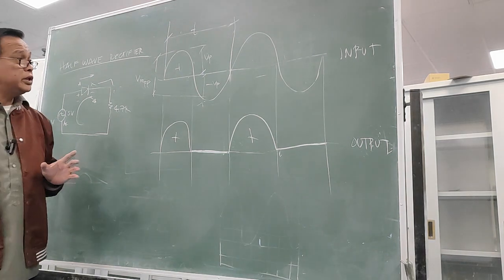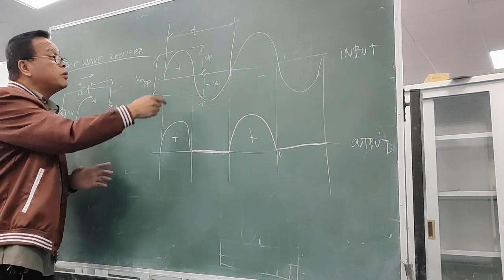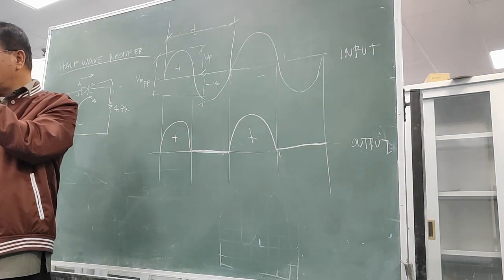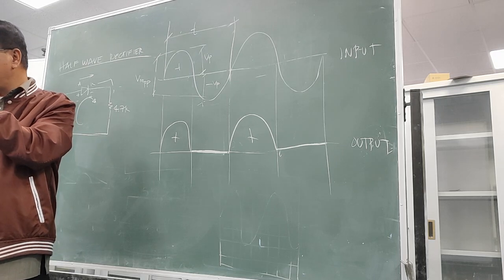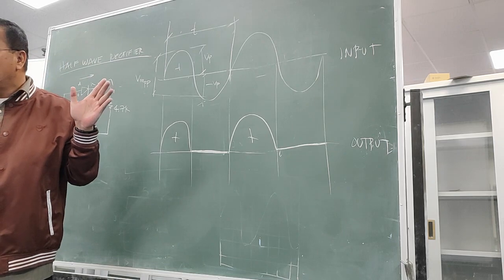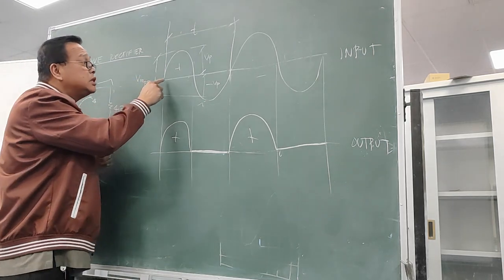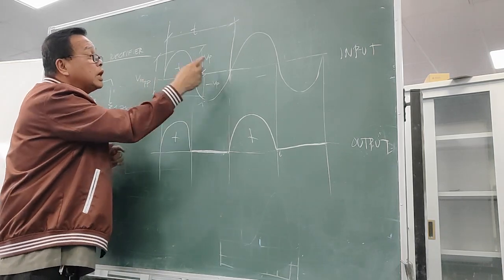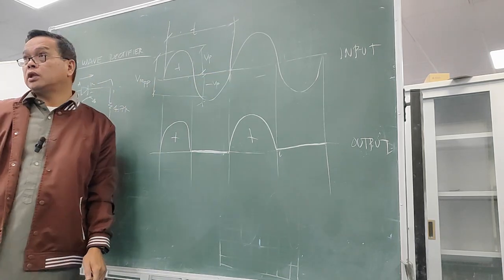Okay? So this one again, on the oscilloscope, you will find here per division. So, based on the range of the oscilloscope and the division, you will find the total time. How much time does this waveform travel from this point until that point?